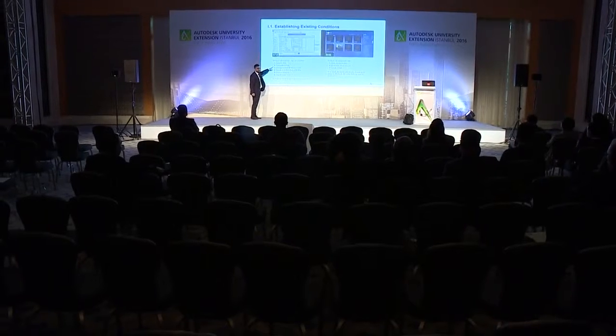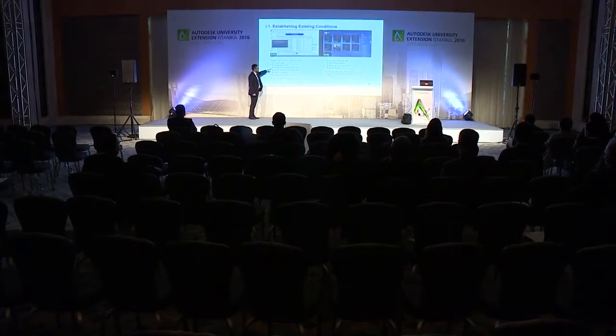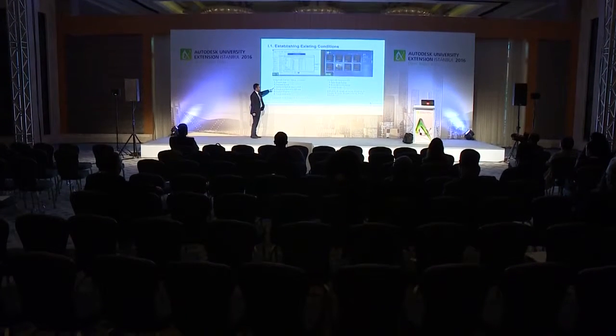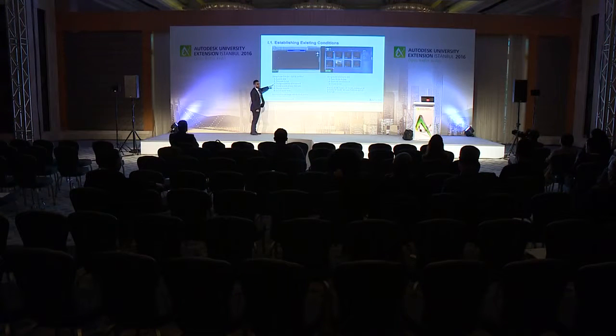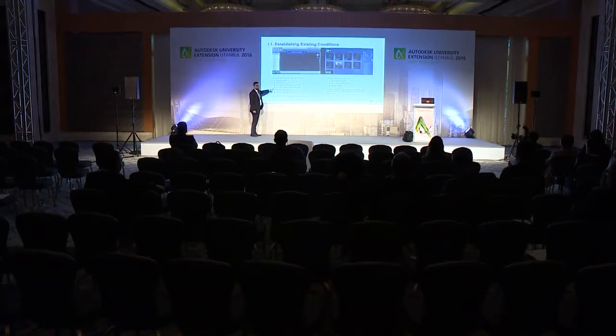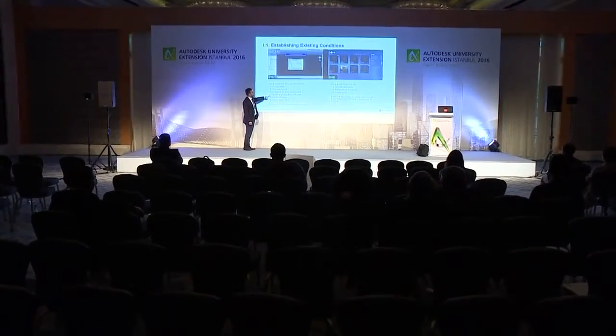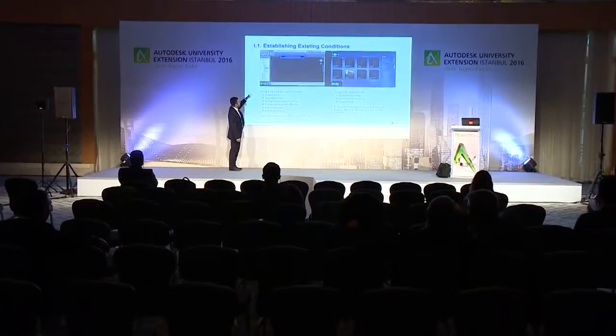The data, we translate it or we configure it. We have to configure the Civil 3D environment, tell it that we're working in this coordinate system, for instance, metric versus imperial, etc. And from the data that we get, we ask Civil 3D to create a surface from the GIS data or the other data that we've got.